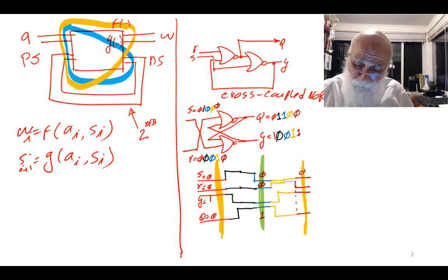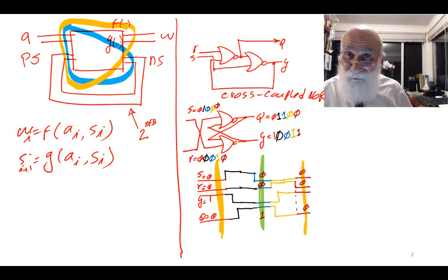Let's look at it here again. This is 0. This is 0. What it means is, in one situation, with the same inputs, my output is 0. In another one, with the same inputs, my output is 1. What has caused this? What has caused this is, obviously, things have happened to my circuit that my circuit remembers. Now look at Y.